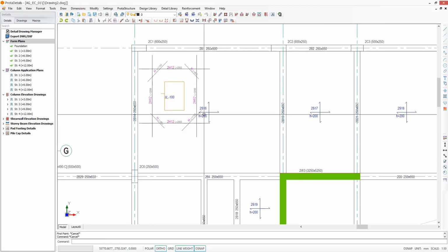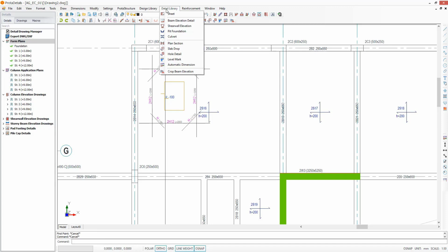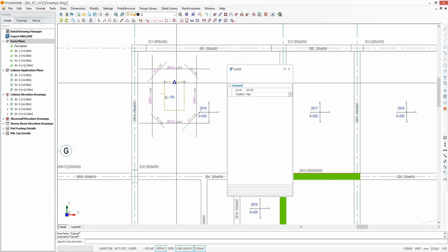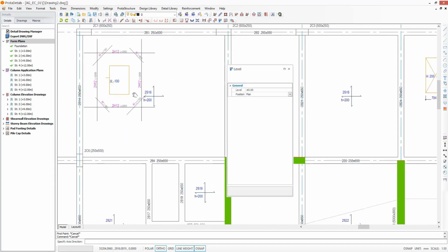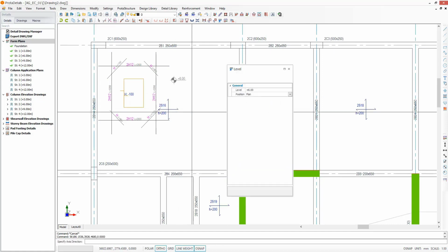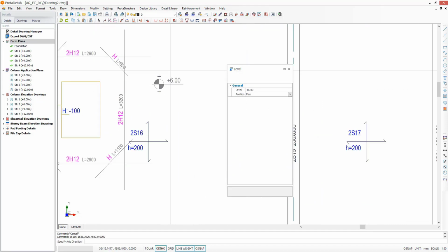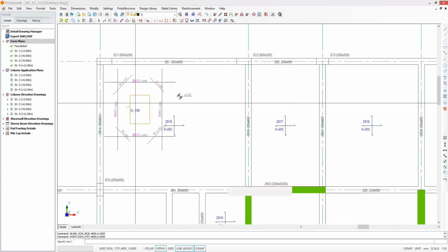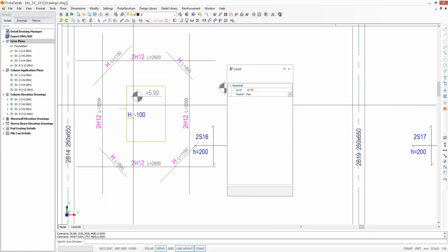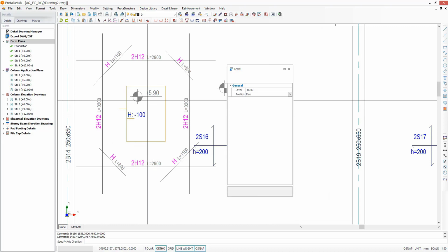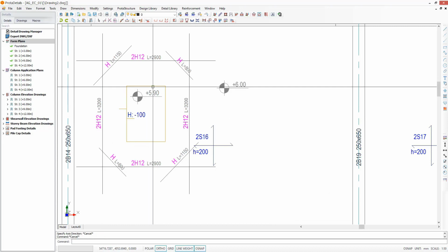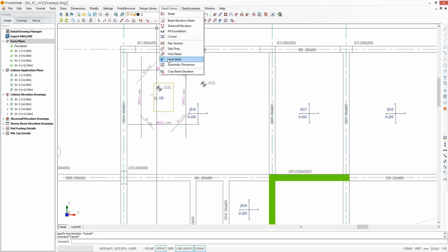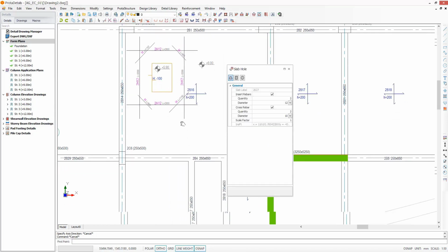And a very interesting feature here is that you can use level marks all around the form plans. So if I click here, I see that this slab is at level 6. But if I click here inside slab drop, it knows that it's a slab drop and it shows the level accordingly. But similarly, let's try hole detailing as well.